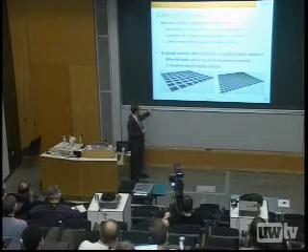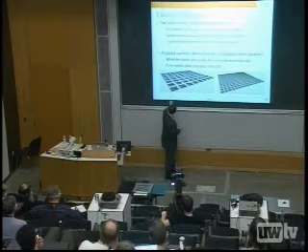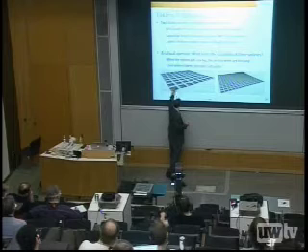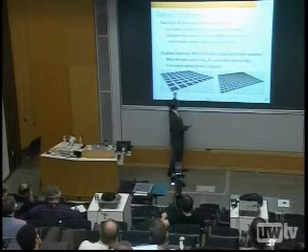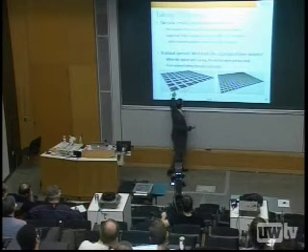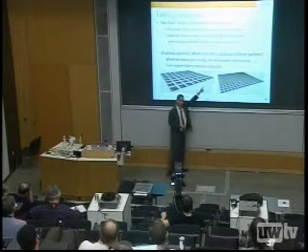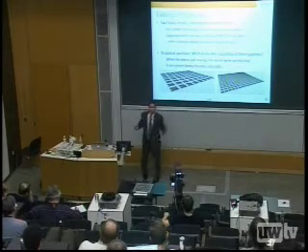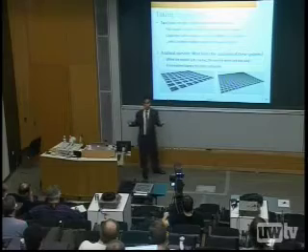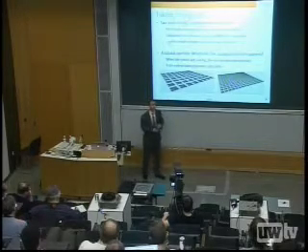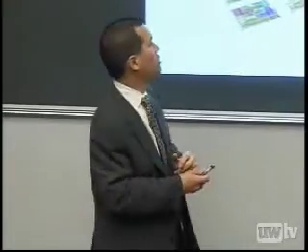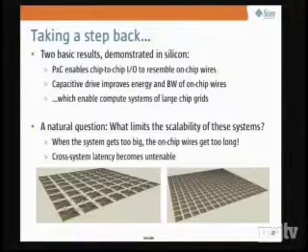But, well, this has a problem, right? Because now, to get from one processor, and some of these may be DRAM stacks, for example, to another chip in the system, I've got a latency that's now quite long. I'm looking at 20 centimeters, 30 centimeters to get across the system, and on-chip wires, I'm sorry, they're just kind of slow for that. So the limitation of the scalability of this really is that the latency of communication across this entire system is going to get too high.